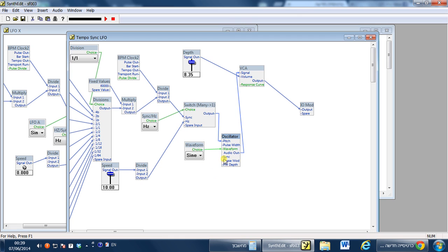All you need to do, this sync input, it also works for oscillator sync. It lets you restart the LFO. So while also good for doing sync functions, it's also great for just re-triggering it using gate. Because the gate signal, when it comes in, will give this input just the value of 1. And whenever this input gets anything that is higher than 0, it knows to perform the sync operation to re-trigger, to restart the oscillator waveform.